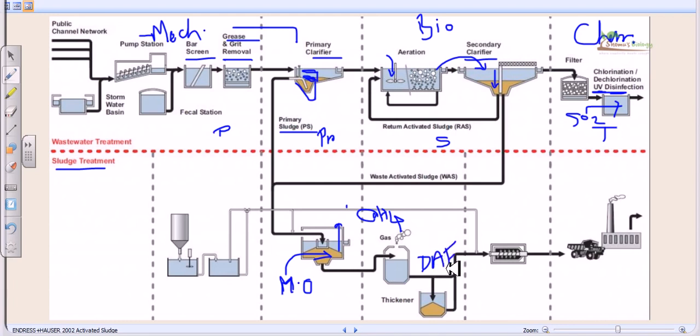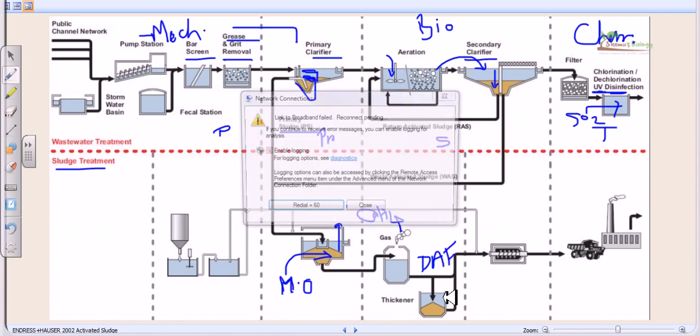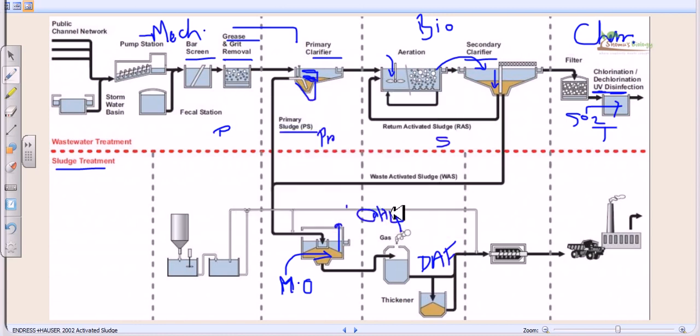Now this type of sludge thickener, what they are doing is, inside a huge chamber, they push the air onto the sludge at a very high pressure, and then just release the pressure so that this sludge will float to the top and the watery part remains on the bottom. As a result of this process, we can have really solid and thick sludge.